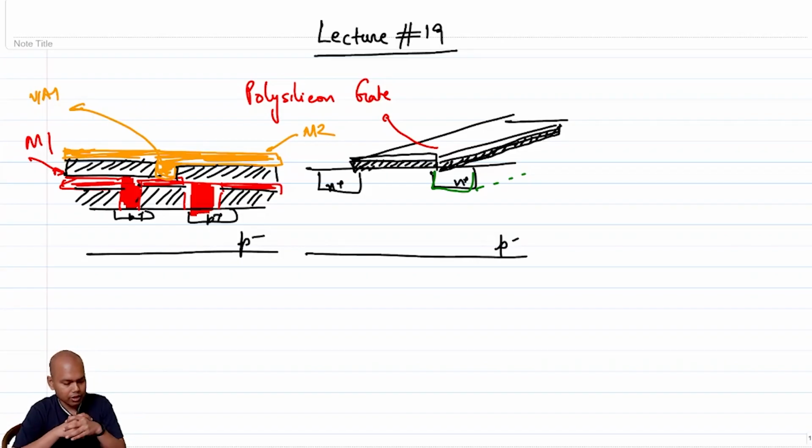So as it turns out, there are several processes which give you metal layers. There are 4 metal layer processes. There are some processes which give you as high as 8, 9, 10 metal layers, right? And needless to say, if your process has more metal layers, it will be more expensive, just like it takes a significant amount of money to build flyovers. Similarly, building flyovers on the chip will also cost you more.